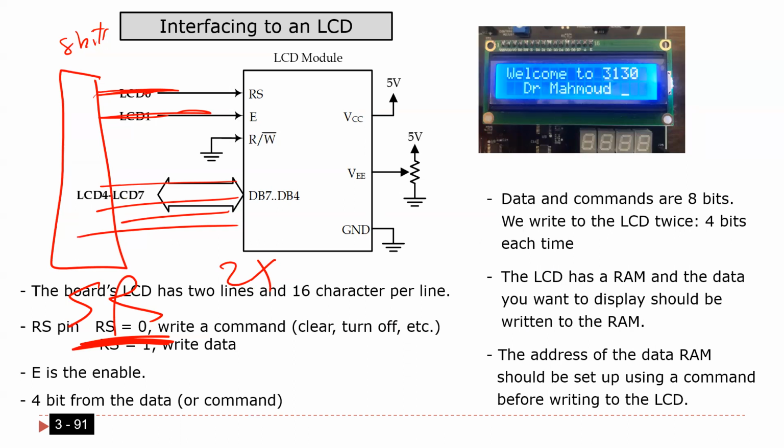Here, if I connect it directly, I need six pins, and I don't want to use 6 pins for the LCD. So the way I did it is, I connected it to a shift register, and then connected the shift register to the microcontroller, and I need only 3 bits. So now I reduced it from 6 pins to 3. But again, nothing is for free. Yes, you reduced it from 6 to 3, which may be good because you can save some pins and connect more peripherals to the microcontroller, but the problem is it's going to be slower. How? I'm going to tell you how.